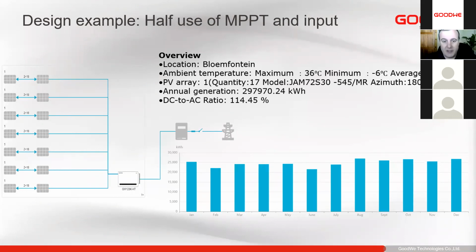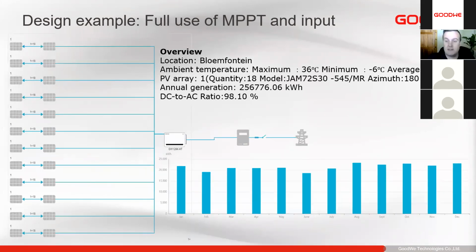So when we connect all of these up, we might see some clipping happening, but this should be within the range of what the inverter can physically deliver per MPPT, and a configuration like this gives us quite a good output with fewer strings. But in a case like this, we will be losing a little bit of efficiency compared to something like this, where we're utilizing all those MPPTs.